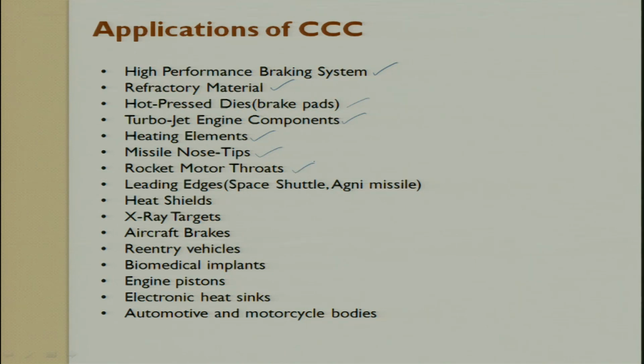The rocket motor throats are made out of it. Leading edge of space shuttles are made out of it. Heat shieldings are made. X-ray targets are made out of it. Aircraft braking system and automobile. Today even in bikes people have started using CC composites.